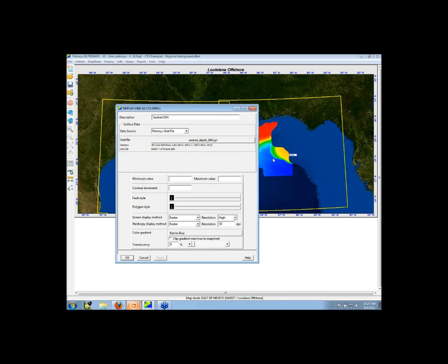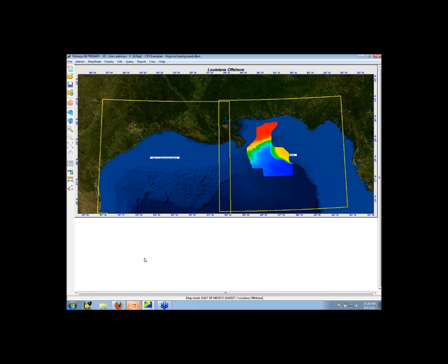It's been applied to the grid, and so it's showing up in the right place without prompting the user for any extra data. And that's really important: to try and tie some sort of CRS information, be it well-known text, which is a definition of the projection system used, or some other form of metadata, to these files, because then GIS applications can know exactly where that's supposed to be.